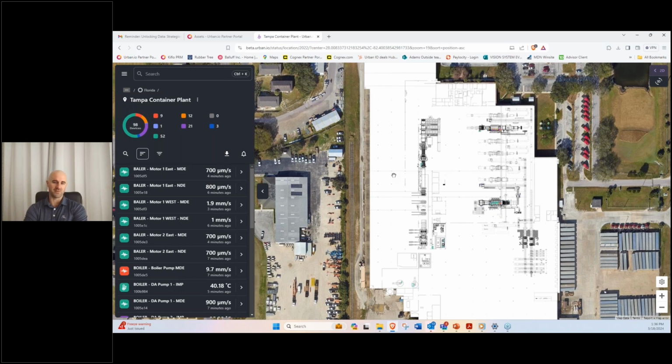So maybe the most metal between it and the gateway. And I go to that gateway and I turn it on and I do a range test. So I could see in my platform, what is my signal strength at this sensor? And if it's above my weakest threshold, then I know I'm probably good at a lot of these other points, but we still do a range test every sensor we set up.